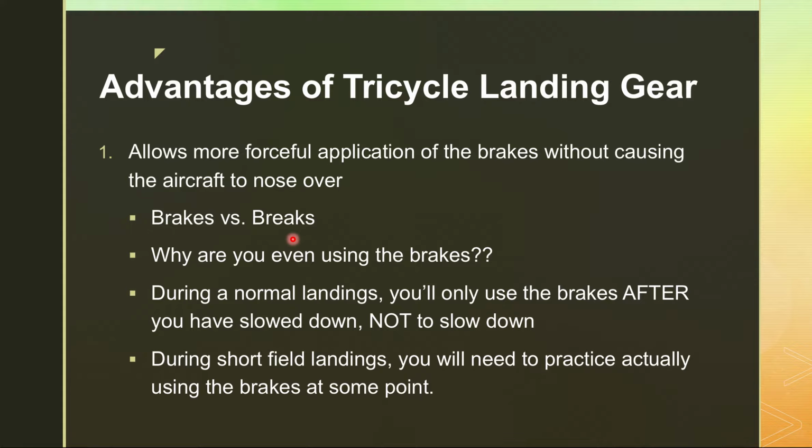You use the brakes when you do your run up. You use your brakes to stay stopped or to slow down after you've already slowed down. Yes, you use your brakes during a short field landing, but as we'll discuss, that's usually done wrong. And you just shouldn't. So basically, I go into Chapter 8 of the Airplane Flying Handbook, and here's what they say. During a normal landing, you only use the brakes after you slow down. You don't use them to slow down.